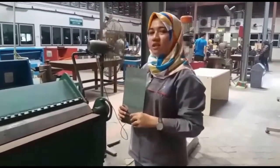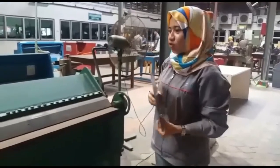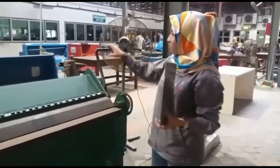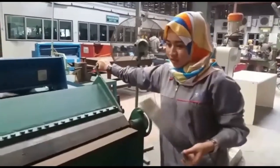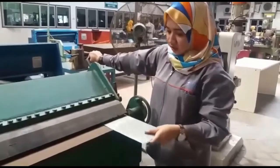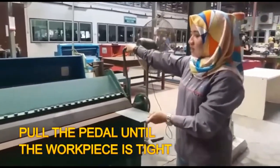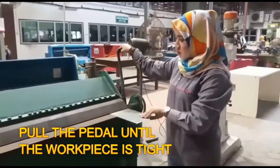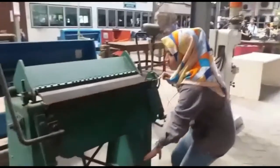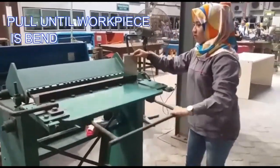Guys, this is the sheet metal bending machine. So it also works manually. So I will show you how this machine operates. So firstly, push the pedal and put the workpiece into the side, and pull the pedal until the workpiece is tight. And then pull this part until the workpiece is stamped.